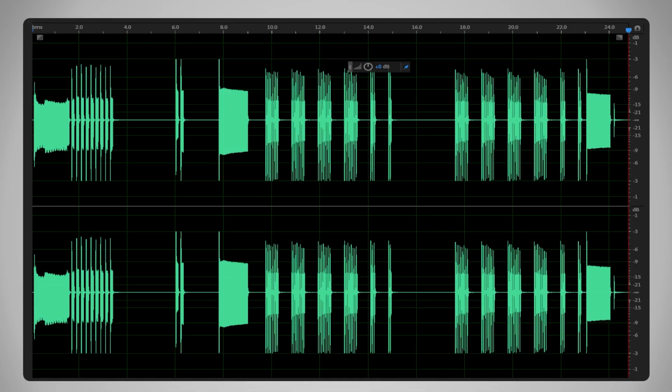You can hear the contact ID handshake first. The radio then moves to the 2300 Hz handshake, and the panel then responds with a 4x2 pulse data dump with a kiss-off from the radio at the very end.